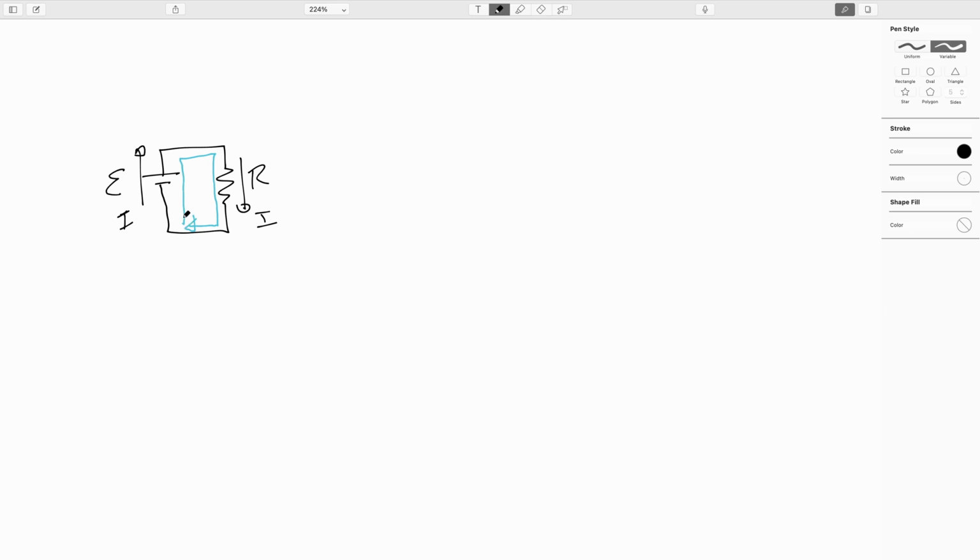So as I walk my dog along by the battery, I leave at the positive terminal. So I would write plus the battery EMF. And then I keep walking my dog along. Wires have negligible resistance, so there's no voltage change.